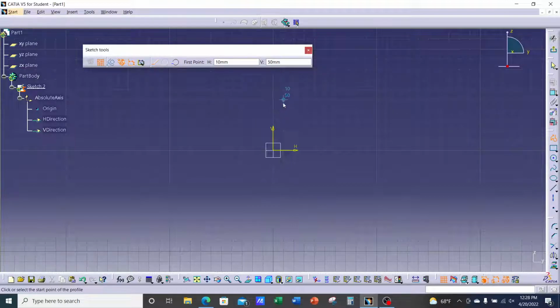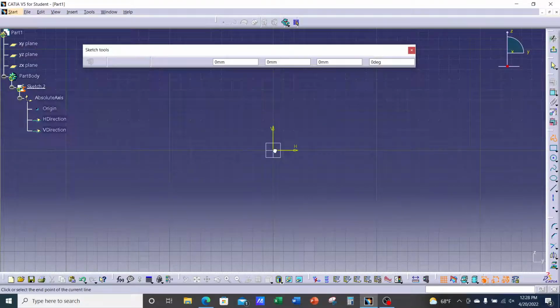Pretty sure you can see it. It's snapping to the grid, right? As you can see, it's snapping to the grid. And I'm going to pick the origin. Notice anytime you pick a point or an endpoint on a line, notice that filled blue circle. It lets you know you're picking a point or an endpoint of a line or a curve. So I'm going to click. Notice how it's snapping. Some of you are going to like that it snaps. When you see blue, that means it's either vertical or horizontal. So I got them mixed up. It's going to be horizontal or vertical, right? Anytime you see blue. Okay, I'm going to turn off this snapping option.